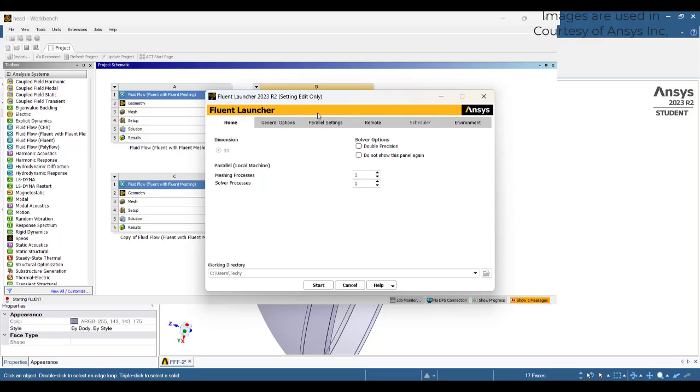In the next video I will showcase how we can handle water vapor as individual DPM particles, and those DPM particles go and stick onto the cold part or the filament or any other part due to the temperature gradient and pressure gradient. On the deposition of those DPM, that will be converted into a Eulerian wall film, and if the Eulerian wall film thickness crosses a particular limit, then it will be